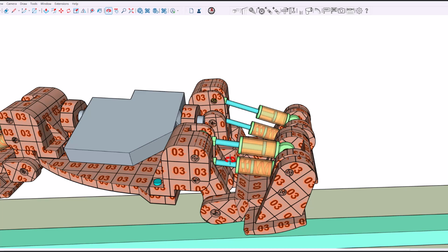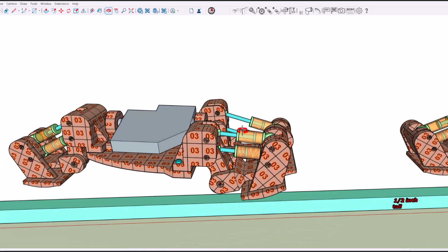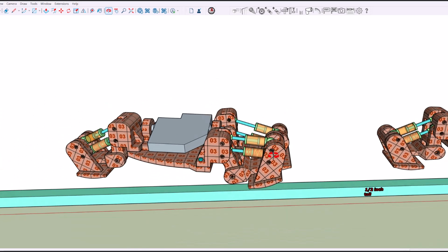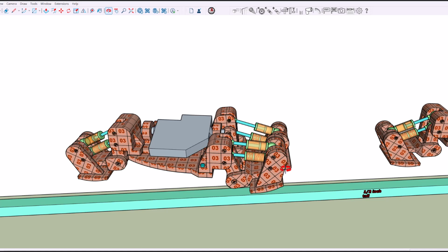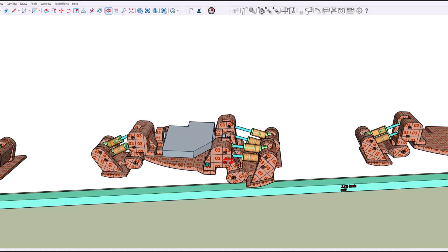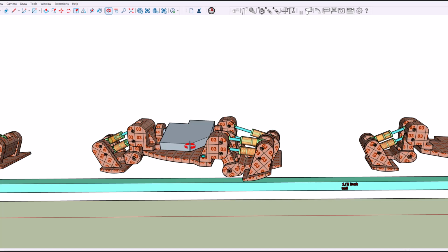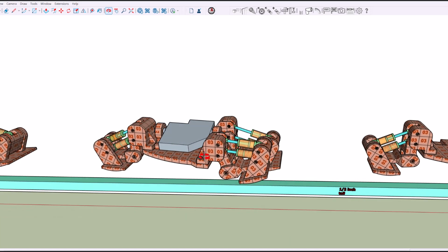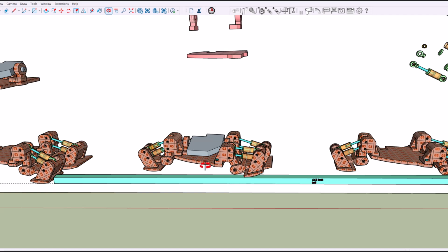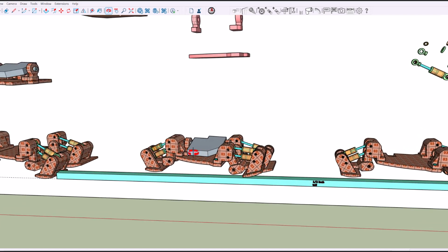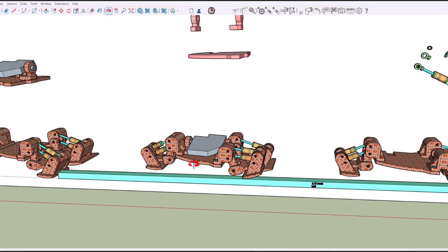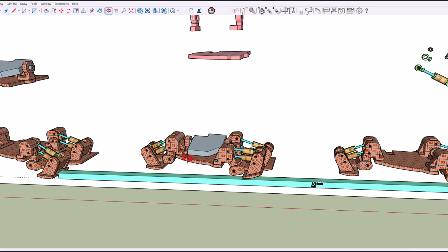And each of these shafts can withstand 1,500 pounds of pressure force on them. So each toe can withstand 3,000 pounds of force. So the three toes can withstand 9,000 pounds of force, and what you're putting on the entire foot is 2,000 pounds of force. So what that means is the robot can let go of the bar, drop 16 inches, and land flat-footed right on concrete, and nothing at all will happen. And this is what you can do if you know the weight of the robot. And so that's what I did.